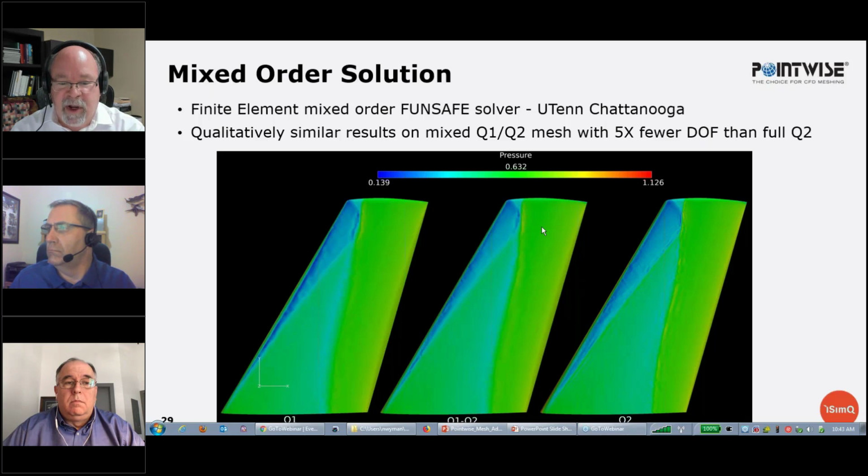And finally, you need some kind of controlling process. We have our controlling process that we've developed together with Pointwise. Run the solver, run the adaptation point cloud analysis to generate the point cloud, run the mesher, all of this in the background, and then repeat until you get to some convergence criteria.